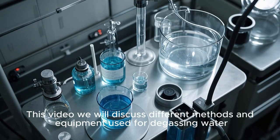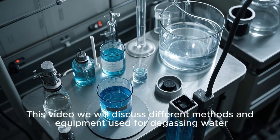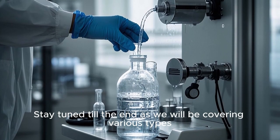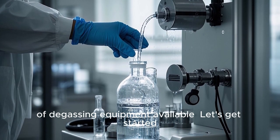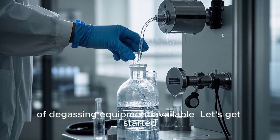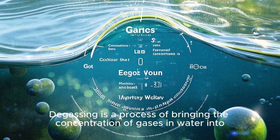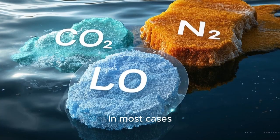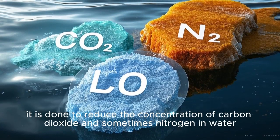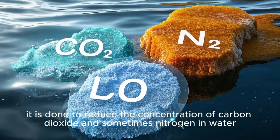In this video we will discuss different methods and equipment used for degassing water. Stay tuned till the end, as we will be covering various types of degassing equipment available. Let's get started. Degassing is a process of bringing the concentration of gases in water into equilibrium with the surrounding atmosphere. In most cases, it is done to reduce the concentration of carbon dioxide and sometimes nitrogen in water.